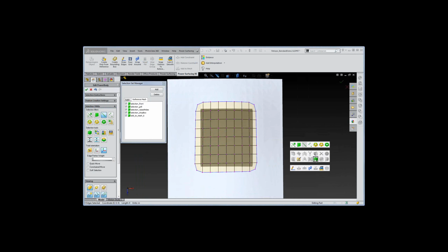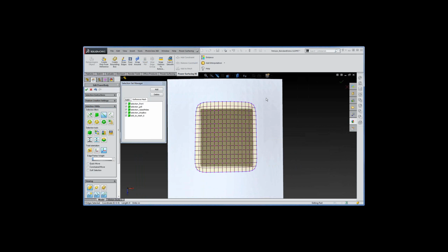and I'll do it maybe a couple of times. And before I get any further, I've got some vertices that are a little bit ambiguous about where they want to end up, and I want to make sure they're pushed off the surface. But now I can go through, and I don't want these to be constrained to the surface because there is no surface below them. So I'm going to select them, and from my right-click menu, this is constrained to mesh, and this is unconstrained. These we want unconstrained. So if I click off them, you can see now they're black, like a regular unconstrained vertex.